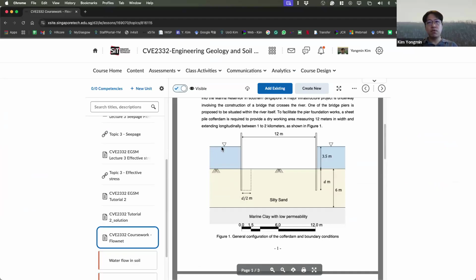Water flows down, it's okay, along the flow channels drawn by yourself, and then starts to go upward. And Terzaghi mentioned that half of D, D is the depth of your sheet pile penetration. Here D. This area is quite dangerous.